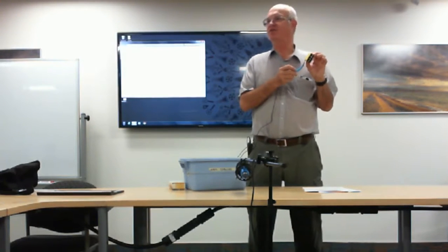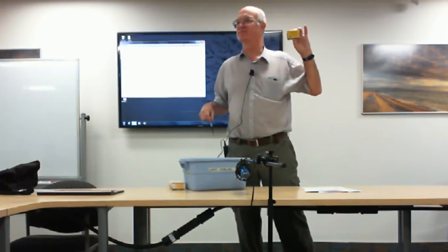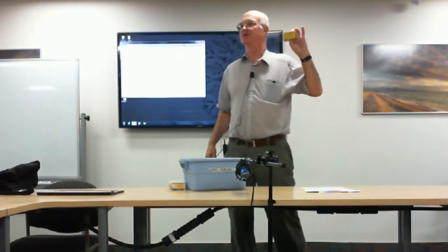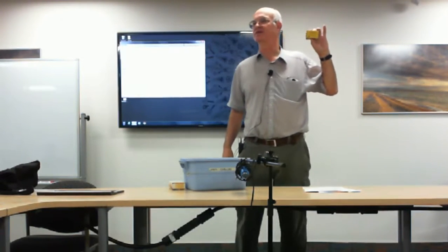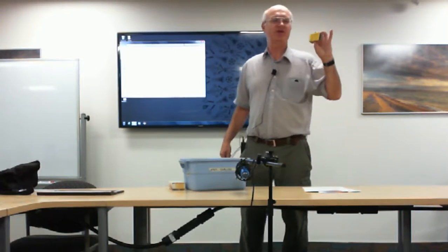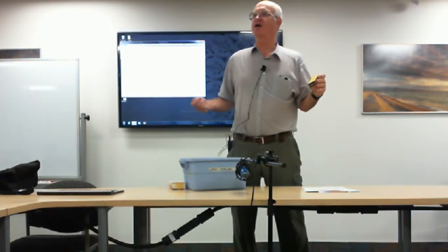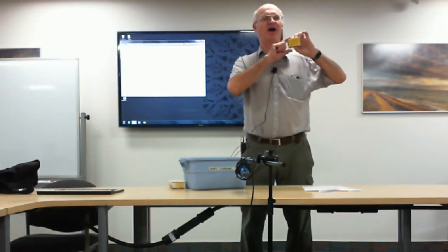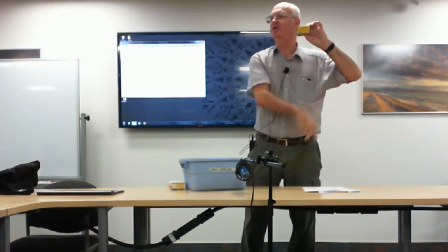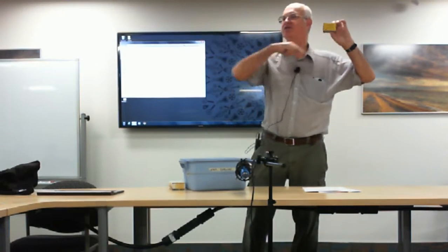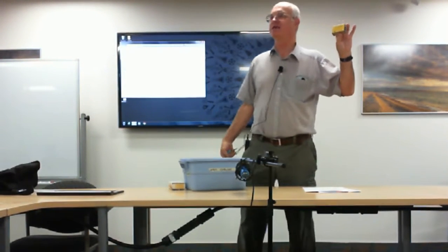Since this is a high-pass filter, where do you think it goes? On which device, the transmitter or the receiver? The device being affected or the device itself? The receiver, yes. This is particularly effective for a TV set because with a TV, you want to pass frequencies that are higher than what you're transmitting. Therefore, if you put a high-pass filter on it, it automatically gets rid of the frequencies below it, so they don't get to come into your set. So you would put this on the TV to block frequencies below the TV band, and you would put that on your transmitter to keep from generating them in the first place as harmonics.